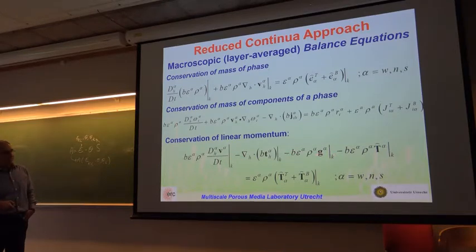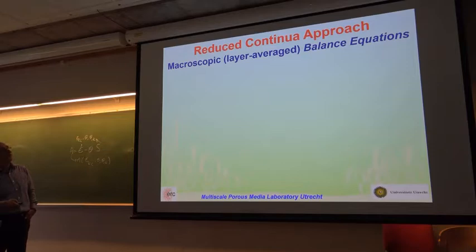And there is an exchange of momentum between alpha phase and other phases in that lateral direction within the layer. So this is intra-layer exchange. And then there are exchange interlayer of the layer of interest, K layer, with K plus 1 and with K minus 1. And these are those, I denote them by top and bottom. This notation was never simple.